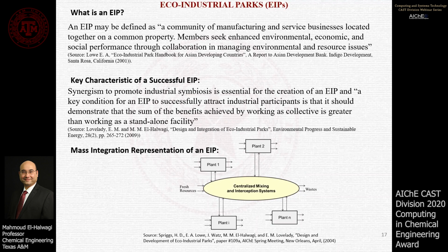An extended form of the mass integration representation that I showed you earlier for direct recycle inside the plant can be used for an EIP, as shown by this representation, developed with Drs. Dennis Spriggs, Ernie Lowe, Jill Watts, and Eva Lovelady. We can use this source, sink, interception, mass integration framework to represent the participating facilities, and the units to be added here referred to as interceptors, and to evolve mass integration techniques to address this multi-scale problem.